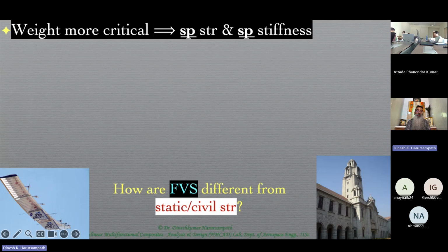Whereas in the case of aluminum alloys and composites, etc., of course, it's a loaded statement because composites have different properties in different directions, but in the desired directions, you would see that the specific properties would be much, much superior, even though sometimes the absolute values of the strength and stiffness might be smaller compared to that of steel or concrete, etc. You would still have, once you divide by the density, you would see that the values are superior.